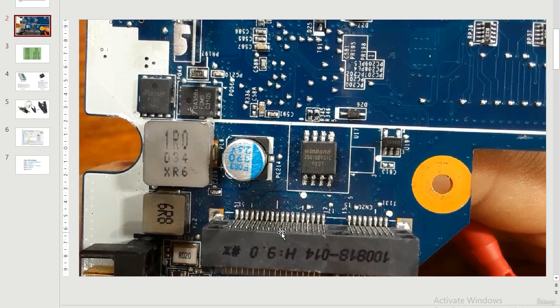So you check all these accessories and all these parts, especially the random access memory. If you check the random access memory, you find it connected correctly to the RAM slot. You check all connectors, you check the hard disk drive, the ODD or the optical disk drive, and you find all of this is installed correctly, but the beeps still persist, which means you should reprogram the BIOS. The BIOS file is probably corrupted.